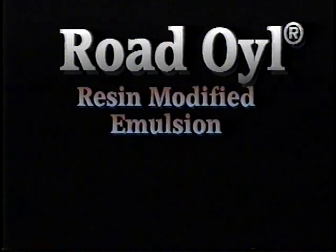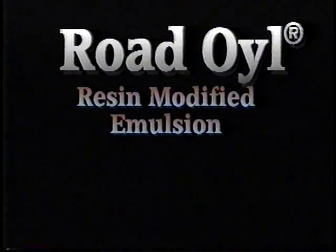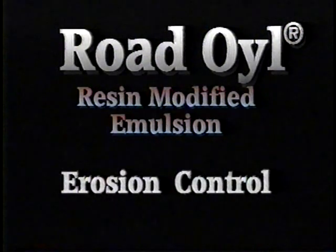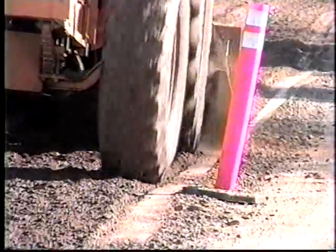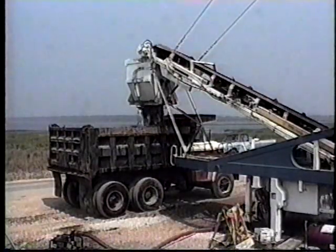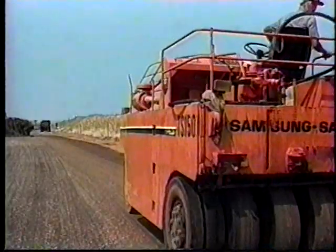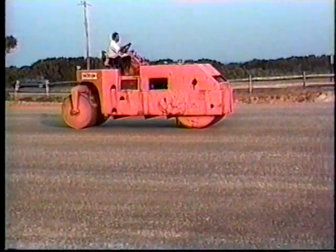Road Oil Resin Modified Emulsion is a non-petroleum, high bonding strength emulsion developed specifically for the construction of pavements, for dust control, and for erosion control. For pavement applications, the non-water soluble road oil emulsion is mixed with aggregate materials already placed on grade, or combined with the aggregate at a central mixing plant and placed with a paving machine. Similar to construction of asphalt pavements, compaction equipment is used to produce dense, smooth-running surfaces.